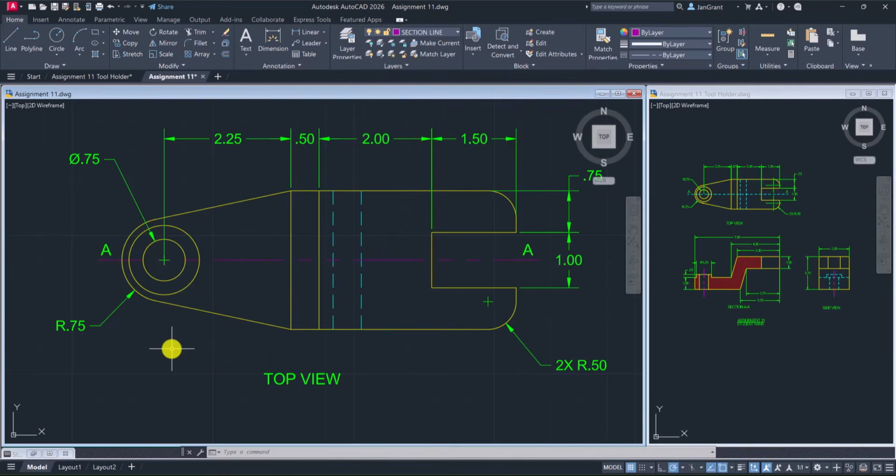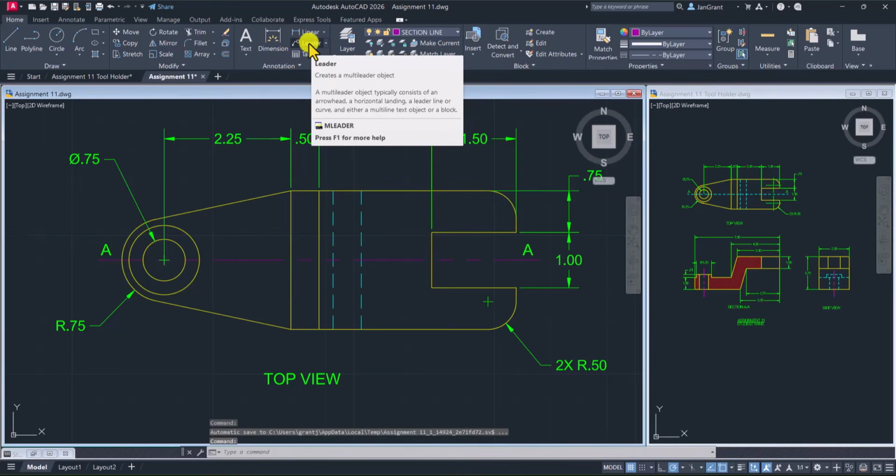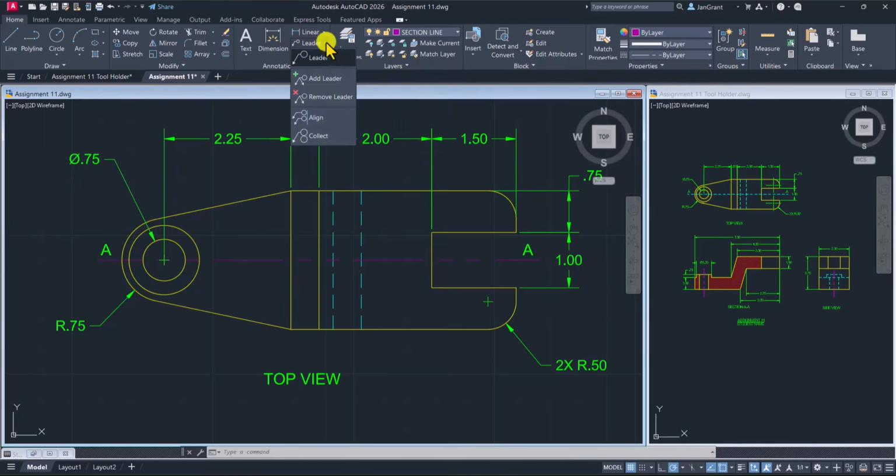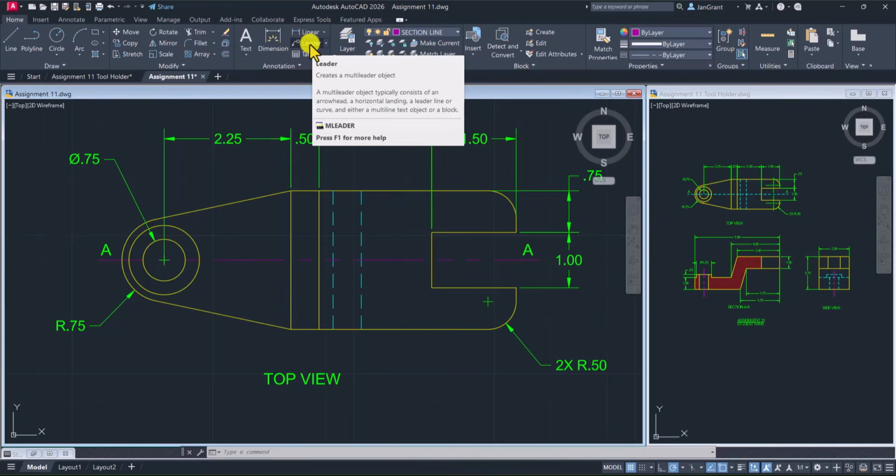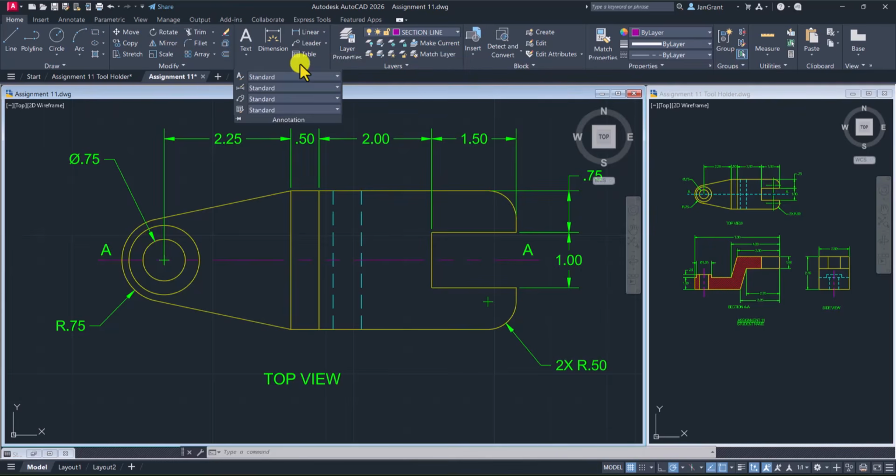I'm going to show you how to draw just an arrow without all the dimension, right? And it's part of using the leader command. We've used the leader underneath linear there for the arrow with text at the end, but we're going to modify it so that it doesn't have the text at the end. So this is a little bit different, but if you go underneath the word annotation right here for that panel that we've been using, these are all of those styles that we can change.